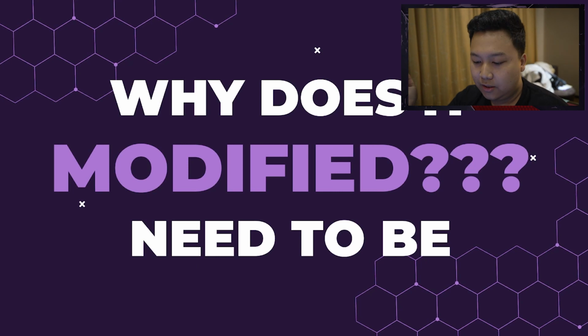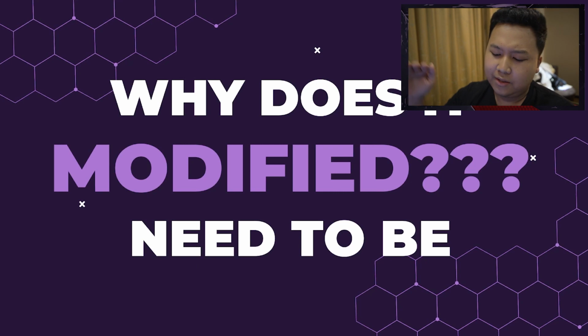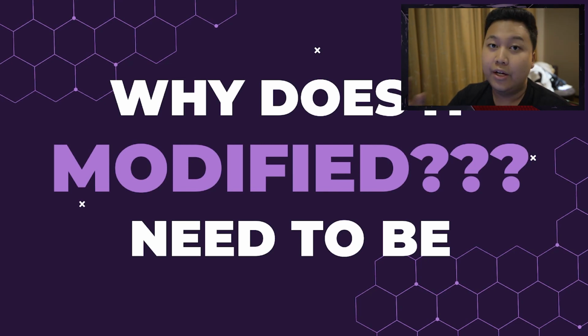For this purpose, the conventional AC bridges such as Maxwell's inductance bridge, Anderson bridge, Hay bridge, etc. are utilized. However, bridge circuits have a limited linear input-output characteristic range. The measurement error caused by stray capacitance between the bridge node and ground and stray inductance of the inductive coils is another disadvantage of the conventional bridge. In order to eliminate the influence of self-impedance of the RX coil, which means the receiver, reduce measurement error and improve signal-to-noise ratio and linear input-output characteristics, it is necessary to modify the Maxwell's bridge.